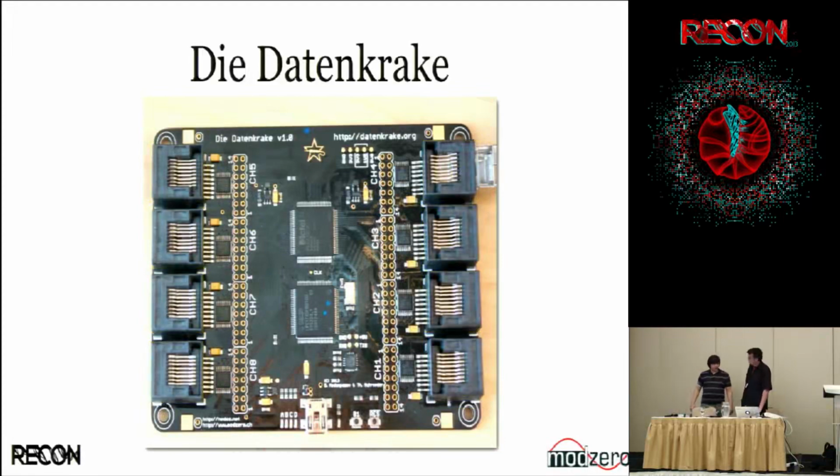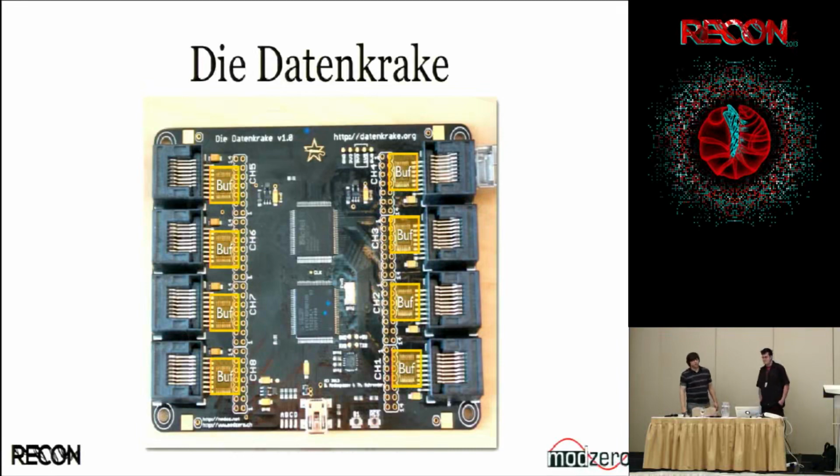But the next thing we have here should be the buffers. So you can see we buffer the signal. This is mainly just to make sure that the FPGA, which isn't as tolerant as certain other things, is protected. These buffers are definitely 5-volt tolerant, and they should work down lower too. I would say, as far as I remember in the datasheet, it should work at maybe 2 or so.